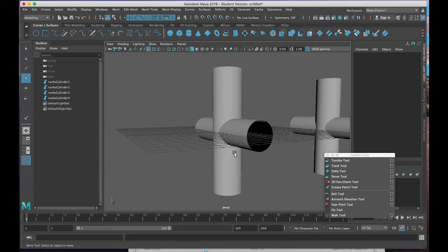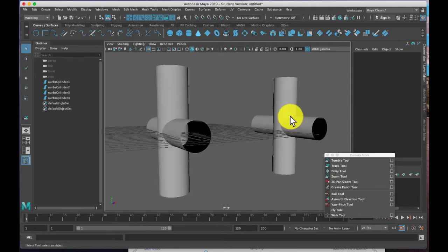In order for us to do this, we're going to go through a process of selecting the cylinders and utilizing the union tool. The process is pretty straightforward. You'll notice right now I've got nothing selected. My Q key, the selection arrow, is turned on, and none of my cylinders are currently selected. I have clicked off into the stage area.